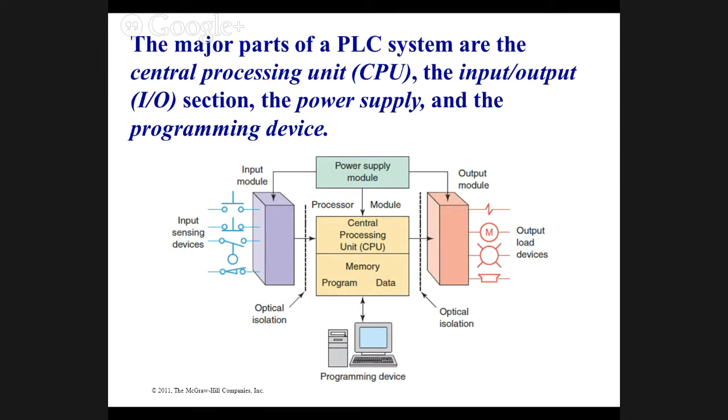All right. So we'll go on, and let's kind of look at this a little closer. I got a question about that one. Does the CPU read from the input first and then go to the memory and then go back? Okay. It's a little different in the new one, but in the SLC 500, first, it scans the inputs.